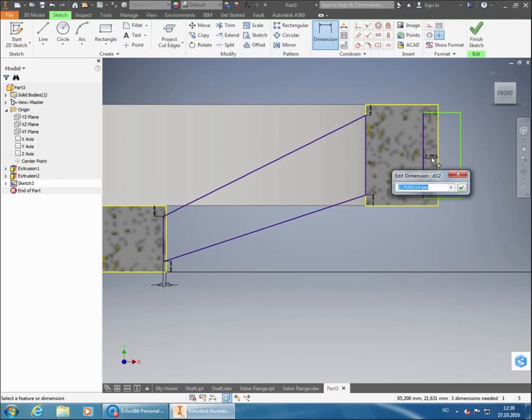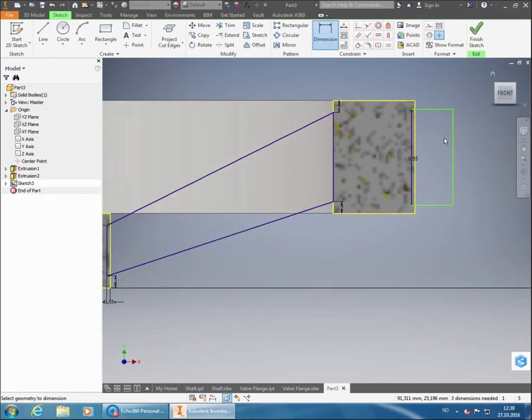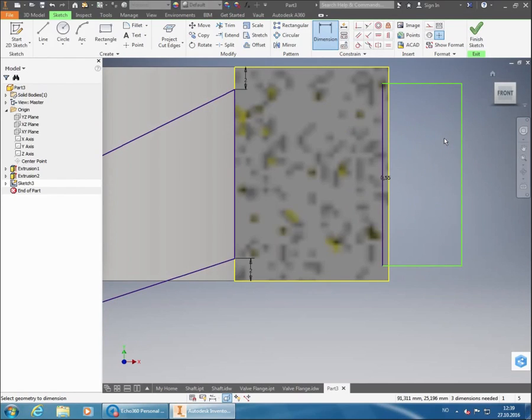And we're going to use 0.55 here also. But then we want this part, which is actually outside the ring, we want that part to protrude 6 millimeters out. So we need to go from the edge of the ring to the edge of the rectangle and set it to be 6 millimeters. Which means that the total width of our rectangle is 6.55 millimeters.